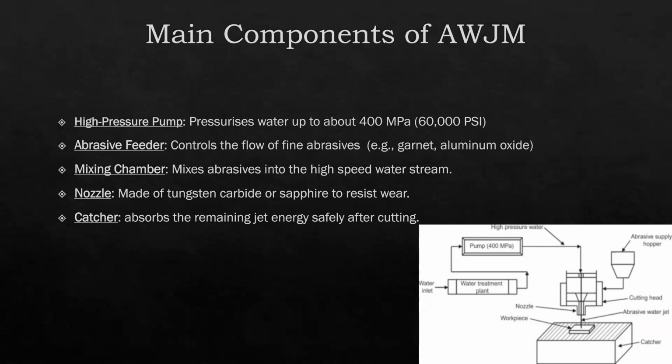Next, we have the abrasive feeder, which carefully controls how much abrasive material mixes with the water so that the stream remains constant. And then inside the mixing chamber, the abrasives combine with high speed water flow to form the cutting jet.